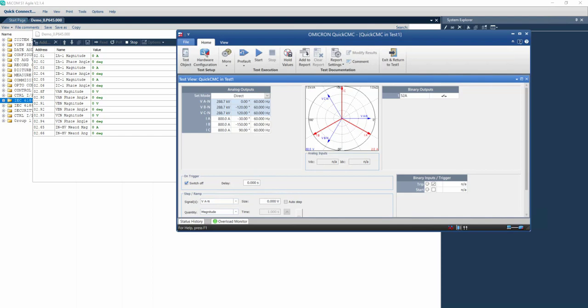In the first video, we explained a brief introduction to the IEC 61850, where we discussed the data model, and we have said that the physical device is a container. That container contains one or more logical devices, each of which contains one or more logical nodes, each of which contains a predefined set of data classes, each of which contains data.